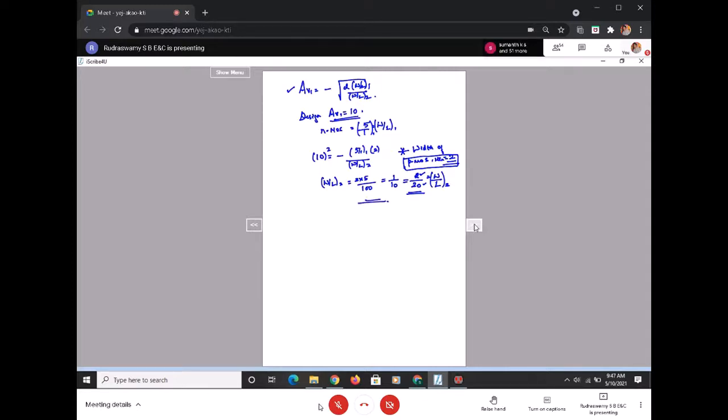Now we'll draw the schematic, and we'll simulate and get the DC analysis first, from where we get the biasing point, and then we find the transient analysis, where we'll see if the input is some value, what the output is, whether we are getting the amplified version, and finally we are going with the AC analysis. Hope everyone is fine till this point.